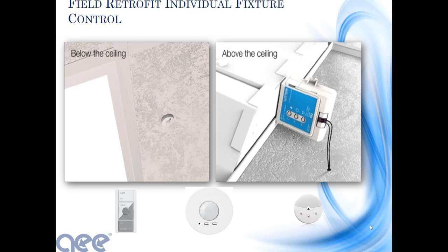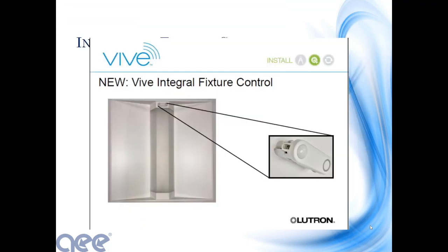Now, the other piece of it, so this is talking about an intelligent driver. The other thing that you can do is there are a lot of manufacturers now that have individual fixture control, luminaire level control. You hear that through DLC. So now you're taking a standard LED fixture with 0 to 10, and you put a box in it that provides the 0 to 10 volt signal and also provides the switching as well. So it's very easy from a retrofit standpoint to get your digital individual fixture control where each fixture operates independently. So this makes a lot more sense from a retrofit standpoint.